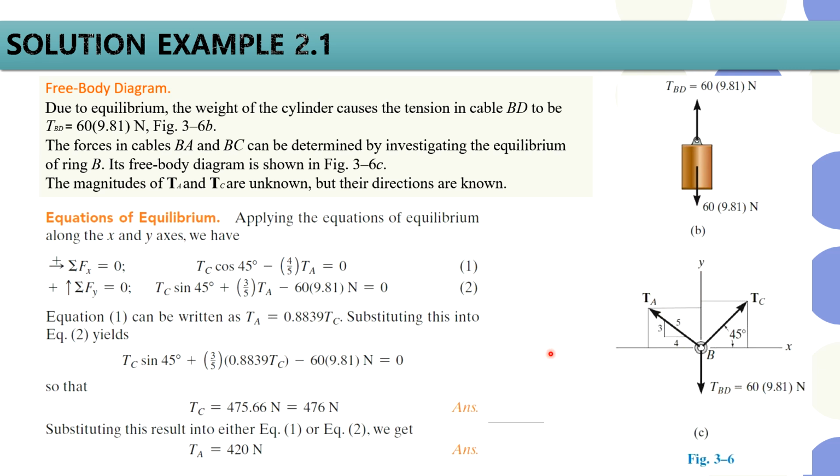Then we apply the equations of equilibrium. For the x-axis, the summation of forces along the x direction equals 0. You need to resolve the tension C and the tension A into horizontal components, meaning along the x direction.